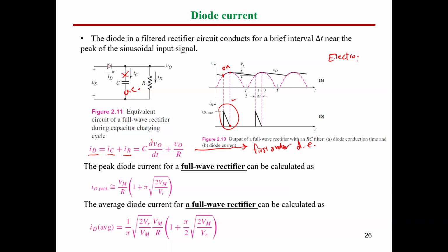The electrolytic capacitor is relatively cheap, and it exists in a lot of products. And the lifetime of this capacitor is very small, like 2 or 3 years at most. If the capacitor is broken, just the lifetime, okay? So you should reserve yourself for the diode. Otherwise, the diode itself will be burned as well, okay?